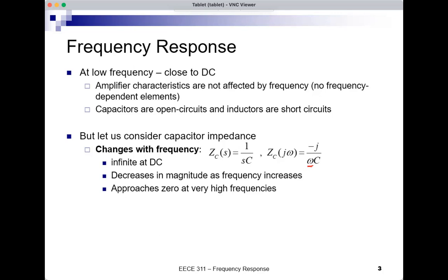So here we have our starting point to understand why the amplifier produces an output magnitude and phase angle that vary with frequency. Maybe there are capacitors in there and their impedances are changing with frequency. And that's really the reason, because there are capacitors in the circuit, their impedances are changing with frequency. And as the impedance changes with frequency, everything in the circuit is now changing.